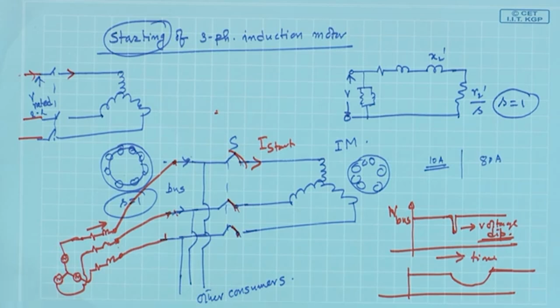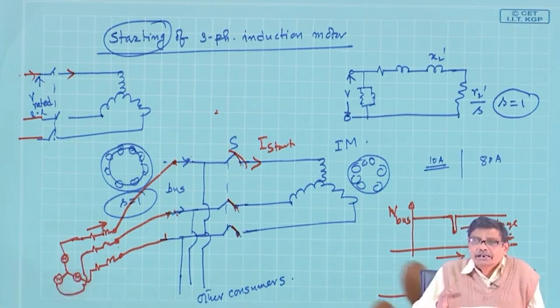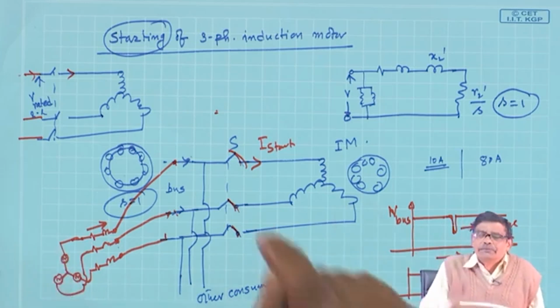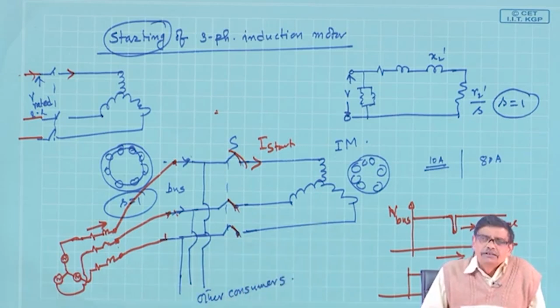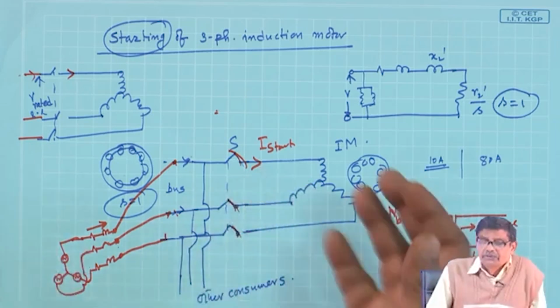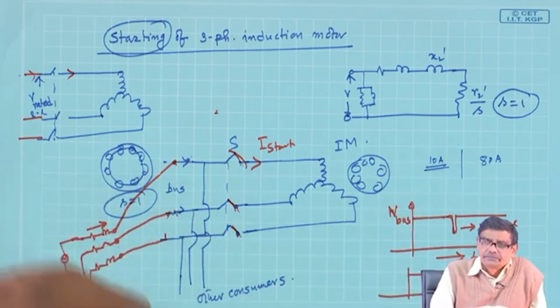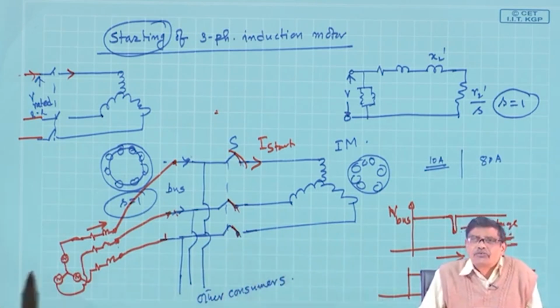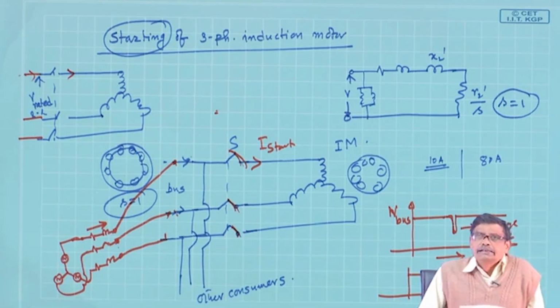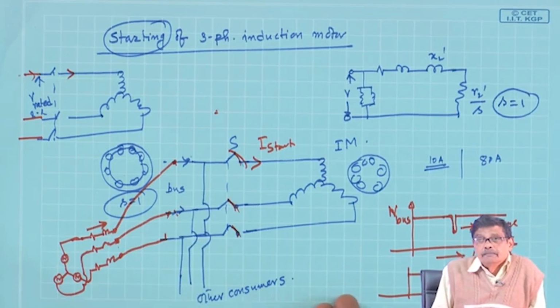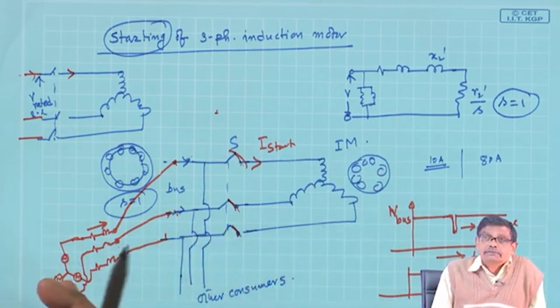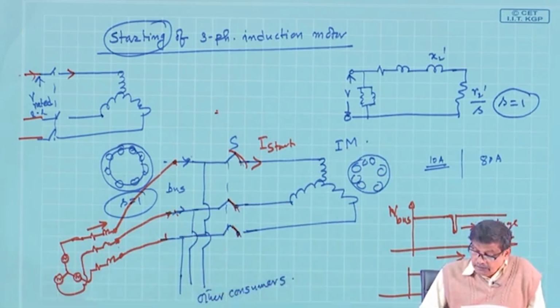But the important point is, if that motor is making on and off in quick succession, I mean very rapidly in small intervals of time, then it will be causing irritation. So, you are reading, working, and every 1 minute there is a fluctuation and once again regaining of voltage, because that is also an induction motor. That you somehow can survive, but fortunately, depending on temperature, there is an auto disconnection of the motor also, so it happens rather not so frequently. But imagine there are critical loads connected to the bus, a hospital, then such a frequent dip in voltage will not be allowed.